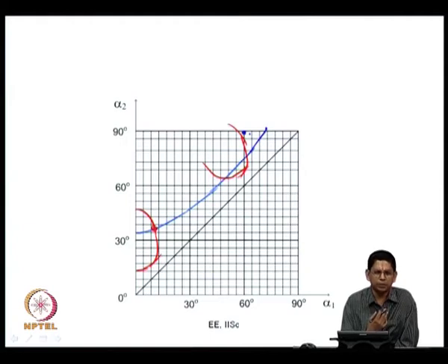You can always come up with some switching angles, for any number of switching angles alpha 1, alpha 2, alpha 3 say, at which the waveform is a third harmonic square wave. That could be a good point to start your solutions many times, because that point naturally satisfies the Vn equal to 0 equation.